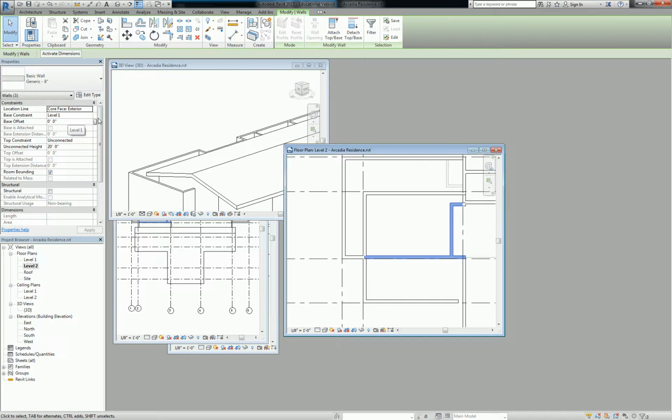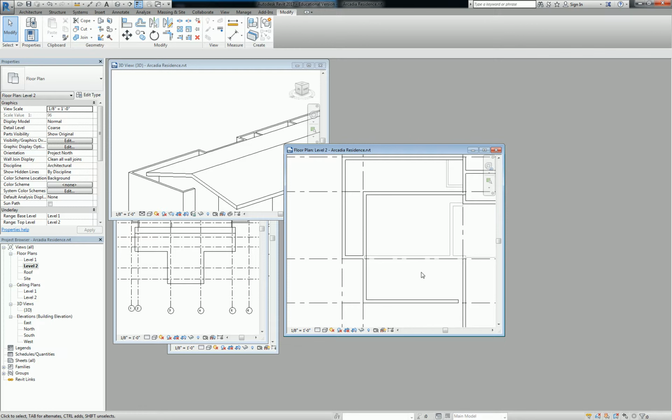We're going to change this to second floor or level 2. And since our floor assembly is 12 inches, we're going to say -1 foot. Is that clear? So that way, if I change my floor level, the top height of that element will move with it. Clear enough? So once I move my mouse out, it grays out, and that's going to be kind of invisible.